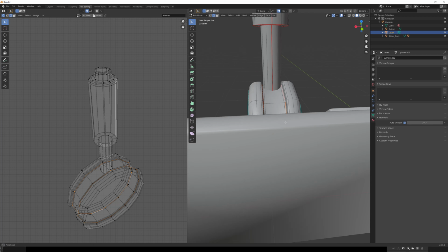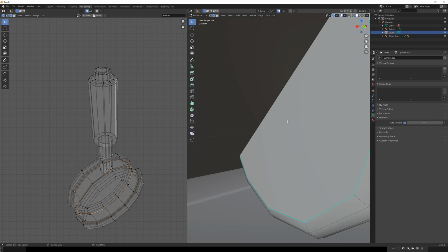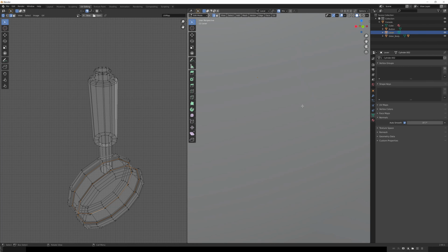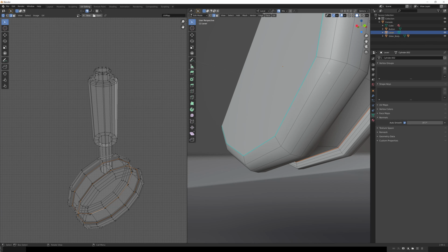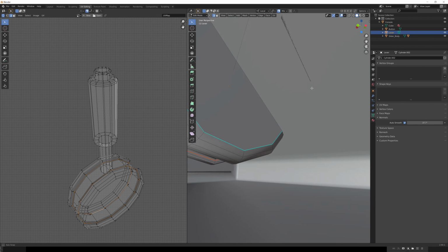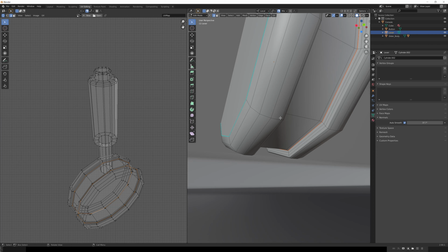And that's going to cut out this central part. Now we do have some geometry on the inside that we probably will never use, but it's okay. Let's zoom in and let's just make a seam, I'm thinking along this edge here. So I'll alt click right there, right click and mark that as seam as well. All right, so let's see what we get.